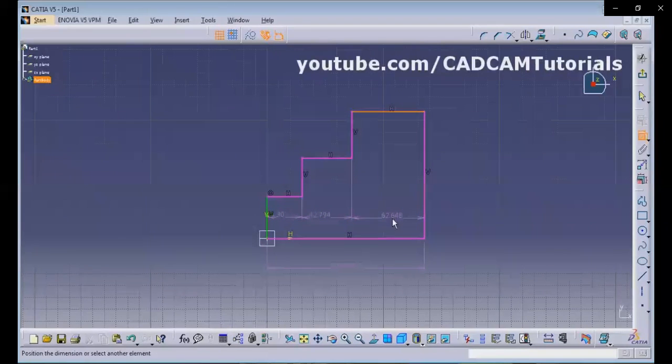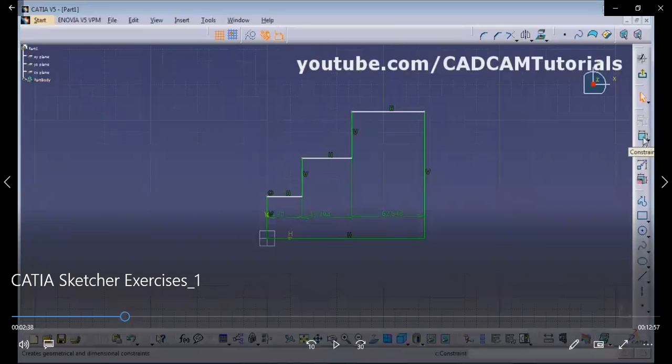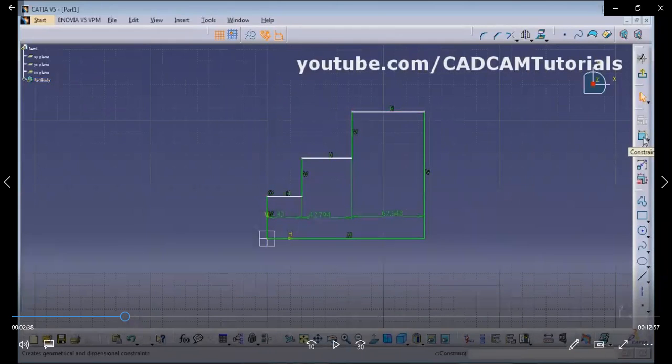Now it became over constrained because we have given this length also. So we will just delete this length. For that we will have to cancel it, select and delete. Then again double click. Why was it over constrained? You see, the color gives you an idea of whether it is constrained properly or not. It was over constrained, right? Why?